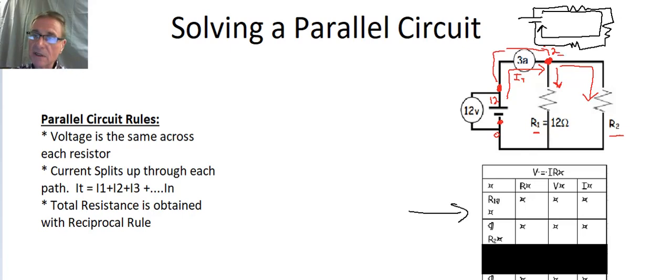Well, and now I can continue along this line here, right? I've still gone through no devices, just along a wire. What have I got right here? Well, I've got 12 volts right there as well. Okay, let's look at the bottom of the battery. Well, I've got 0 volts down here. Well, if I trace a line over here and I get to this point right here, how many volts do I have there? Well, I've got 0 volts. I continue along here, going just through the wire now. All right, no voltage drops or anything. How many volts do I have here? I've got 0 volts there as well.